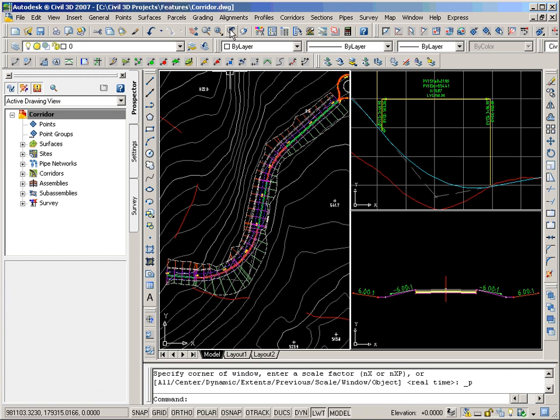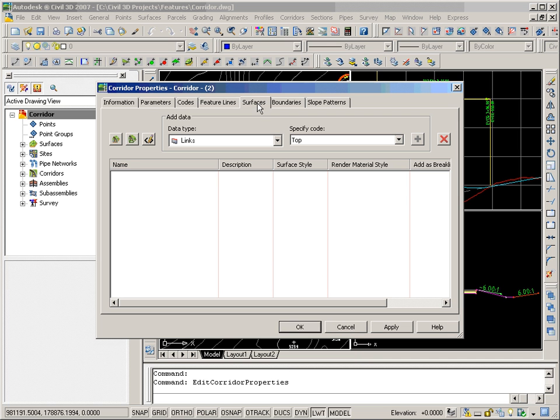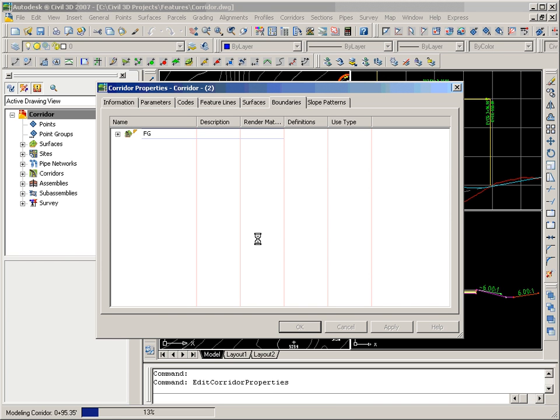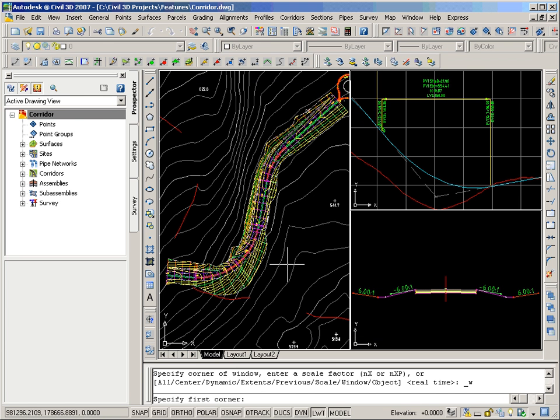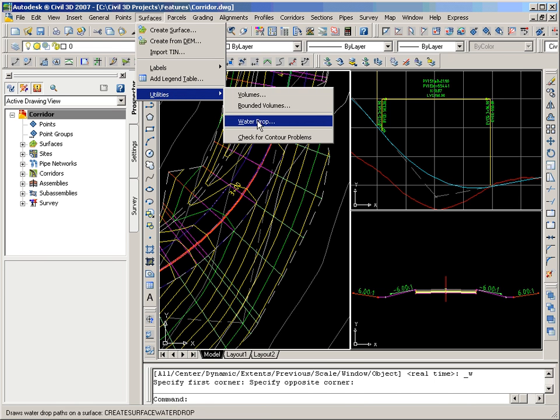Next, we can quickly generate a surface from this model and use it to calculate volumes of cut and fill for the design to see if adjustments are needed. We will use a simple calculator to compare the new surface with the existing ground and get both cut and fill volumes. With this analysis, we can then adjust the design and try to compensate for these volumes and begin to balance them out.